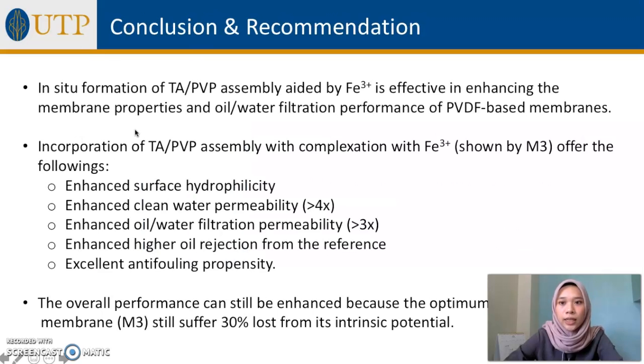So in conclusion, I can say that the in situ formation of the TA-PVP assembly aided by iron 3+ is effective in enhancing the membrane properties and the oil water filtration performance of the PVDF membrane. As we can see from the results shown by M3, the incorporation of the TA-PVP assembly with the complexation offers enhanced surface hydrophilicity and enhanced clean water permeability, which is 4 times higher than the pristine PVDF membrane. It also shows enhanced oil water filtration permeability, which is 3 times higher than the pristine PVDF, and also enhanced oil rejection performance and anti-fouling propensity.